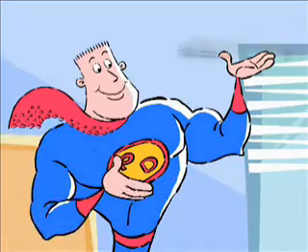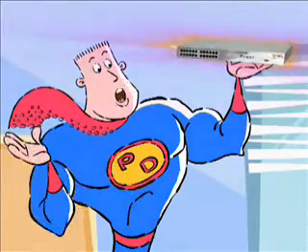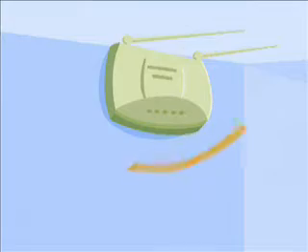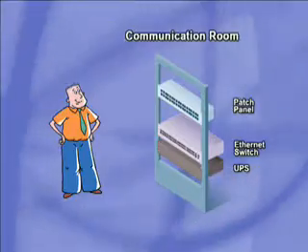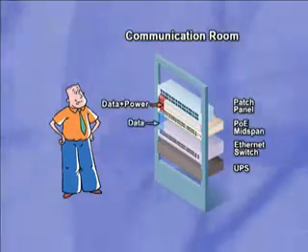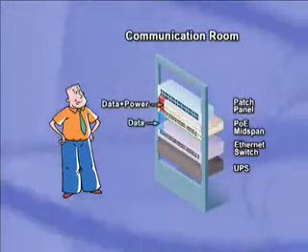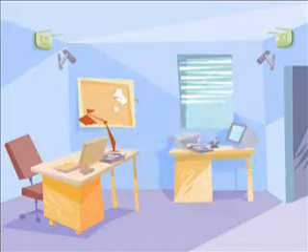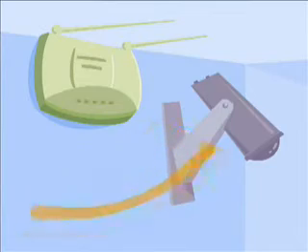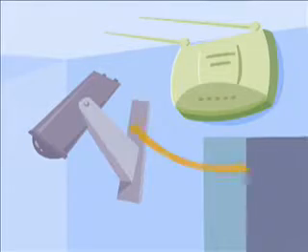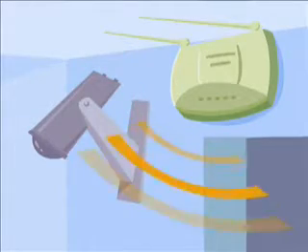Don't forget, midspans are just as essential in wireless LAN and security applications. They work in exactly the same way. You put the midspan of your choice in your communication cabinet next to your switch and UPS. This means you can install any wireless access point or security camera exactly in the optimal spot and extend the Ethernet run from the switch to the remote device.